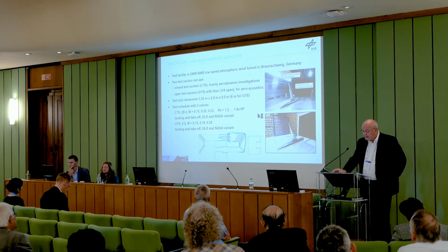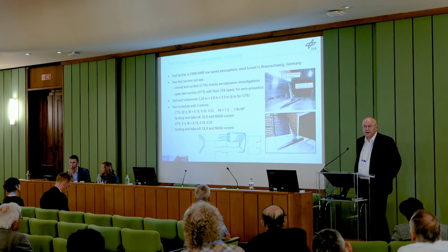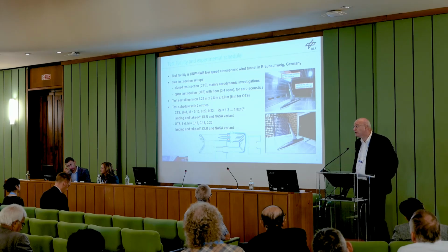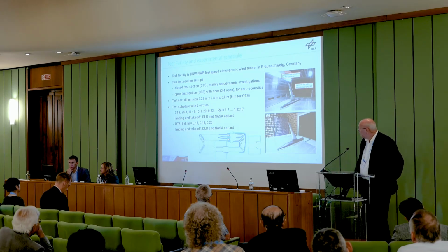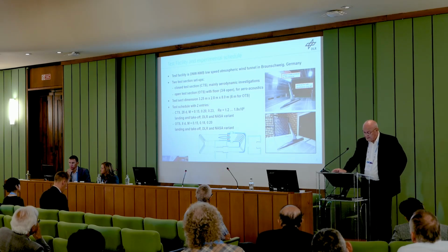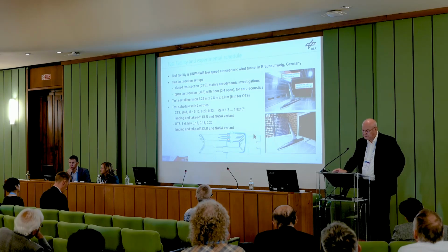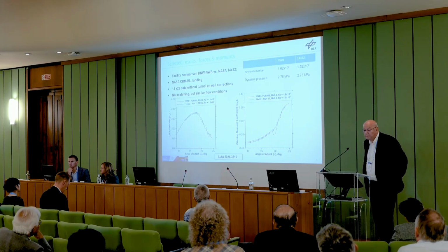You see the open test section down here. We have a semi-span model which needs to be mounted, so we took a floor, and this setup is designated as 3/4 open, if you will. And you see also the anechoic chamber, so the tunnel has fairly good acoustic properties, I would say. And on the sketch, you see the closed test section, and this is the anechoic chamber and the open test section down there. All right, let me come to the results.